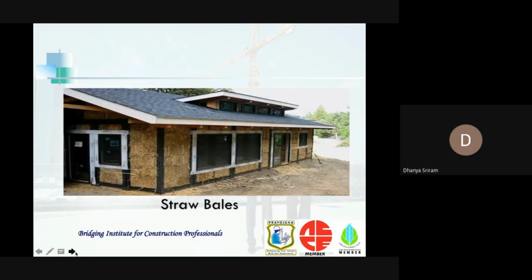Straw bales are used to create home walls inside of a frame, replacing other building materials such as concrete, wood, gypsum, plaster, fiberglass, or stone. When properly sealed, straw bales naturally provide a very high level of insulation for hot or cold climates, and are not only affordable but sustainable, as straw is a rapidly renewable resource. Rather than relying on new research and technology, straw bales take us back to the days when homes were built from naturally and locally occurring materials. Next is